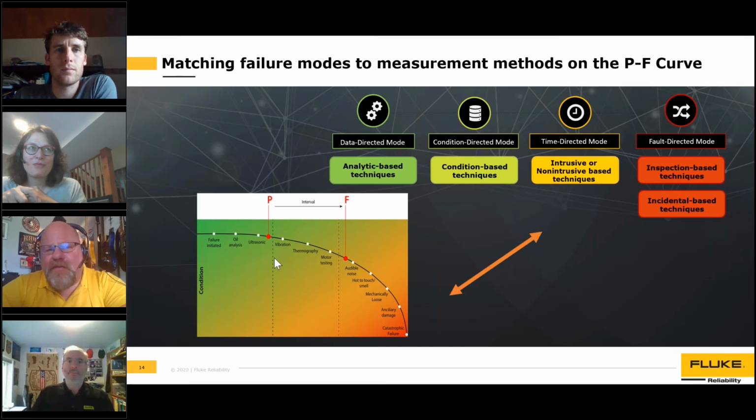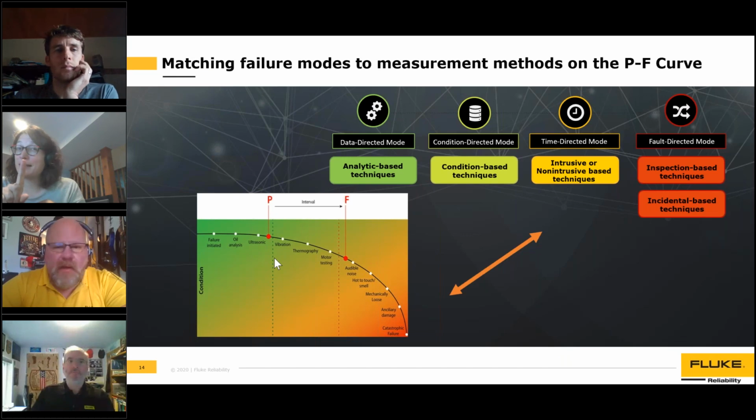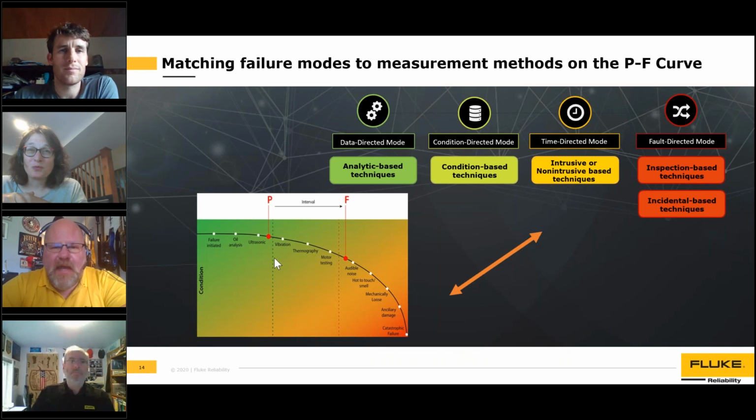But we have defined, when we go in and we actually do our FMEAs and our FMECAs or any other technique that you can apply, what we do find, and what we want to define, is the functional failure point. That's what classic RCM, Nowlan and Heap, that's what we talk about, especially with RCM2, with Moubray. What do we understand about functional failure? If I have a pump that's 120 gallons per minute, and that is the design state, and it's now pumping 119, it has functionally failed. But has the pump failed totally?